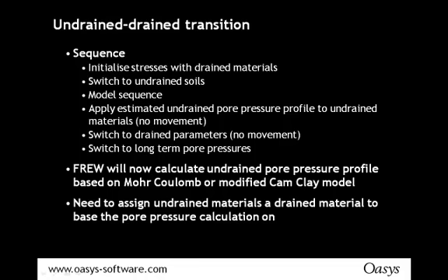So I'm now going to go on to the undrained to drained transition. And there's a specific sequence that has to be followed with the undrained to drained transition. In this sequence, you initialize the stresses with the drained material. You switch to the undrained soil, so you set the pore pressures and you switch to the undrained soil. So you model the sequence.